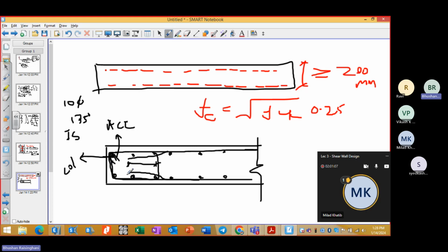The spacing would be a maximum, so minimum 100 center to center of the stirrups, a 135 degree angle of the bend, and it has to have adequate diameter. And the third part is related to whether it is required throughout the length of the column or not.